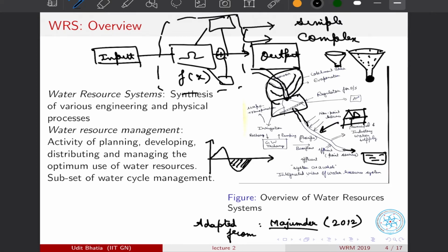Also, when we build dams, we are collecting a lot of water at one specific place, or we are having stagnated water. And when water is stagnated, some water will go down into groundwater in the form of groundwater recharge, and some water would also go as evaporation. And now, you know that whenever water surface area increases, the rate of evaporation also increases. Also, when a large volume of water is in contact with ground, it would be able to recharge or percolate deeply, and hence we have to account for these losses whenever we try to model these systems.